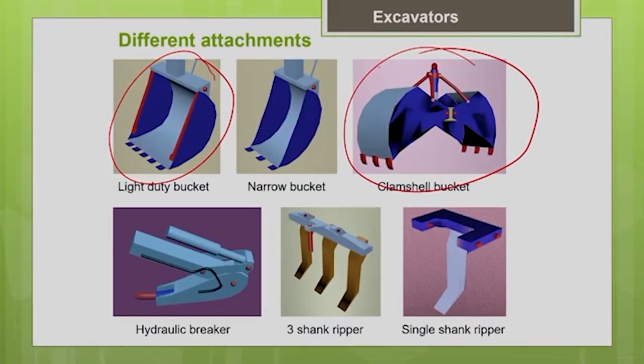I can use it for trenching or excavation of material from a manhole sewer, or I can use it for excavation from a pier foundation. Okay, so wherever I need some vertical digging, I can use this clamshell arrangement. So this is also a very popular attachment. So as I told you, this can even be mounted on the cranes.